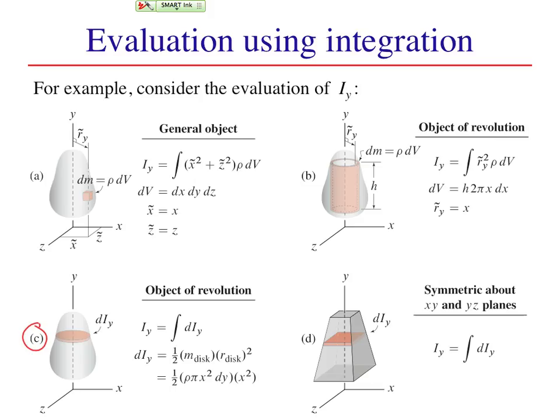We had previously stated without proof that an increment of polar mass moment could be written as dI_y equals 1/2 dm times the radius of the disk squared, which gave us this result. Our thin plate results can also be used to generate this same expression. Now the plate thickness becomes infinitesimal, so t goes to dy, and the mass moment goes to an infinitesimal mass moment dI_y.